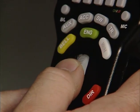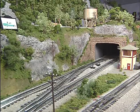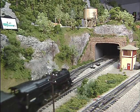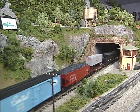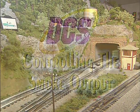When you have chosen the desired volume, press firmly on the thumb wheel to set that volume. Your engine will remember its set volume levels even when it is turned off between uses or when operated in conventional mode. Follow this procedure anytime you want to change the volume settings.